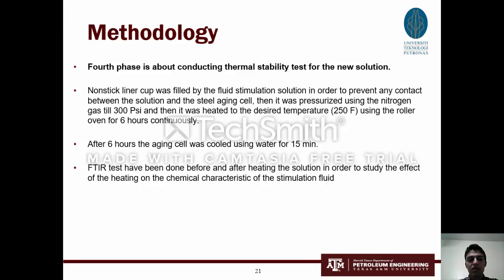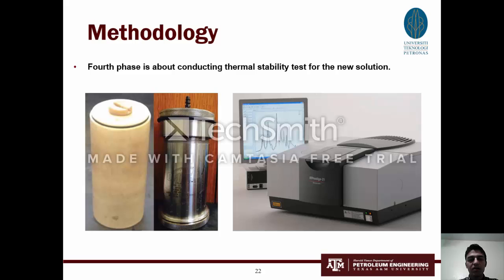After 6 hours, the aging cell was cooled down using water for 15 minutes. FTIR tests were done before and after heating the solution in order to study the effect of the heating on the chemical characteristics of the stimulation fluid. Here is the linear plastic cup, the steel aging cell, and the FTIR equipment.